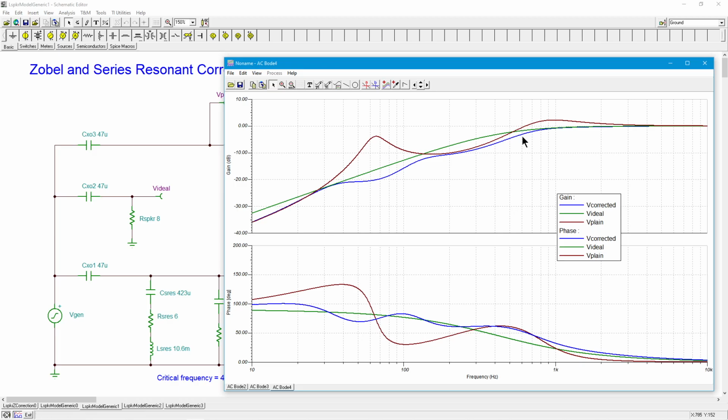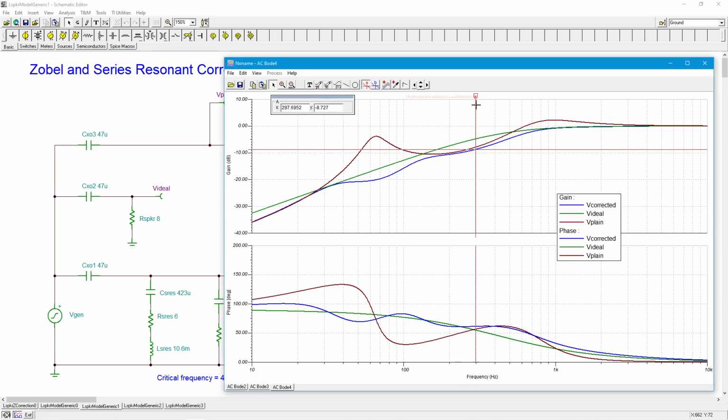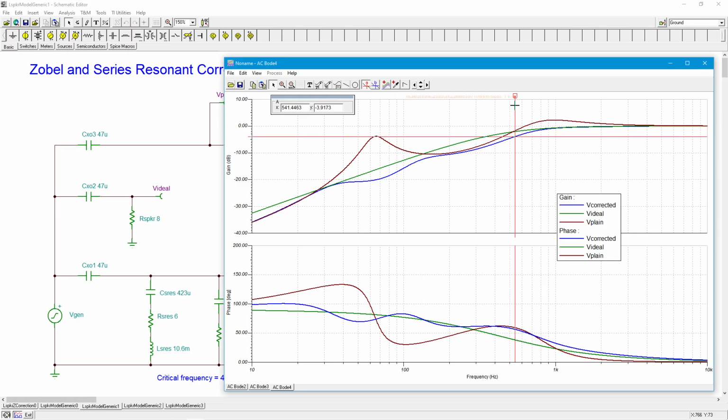I think we had like 420 some odd hertz, right? In a way, you could think of this as just a raised critical frequency. Like the frequency has been shifted. So where's -3 dB for this? All right, close enough, right around there. Yeah, it's like 600 hertz.